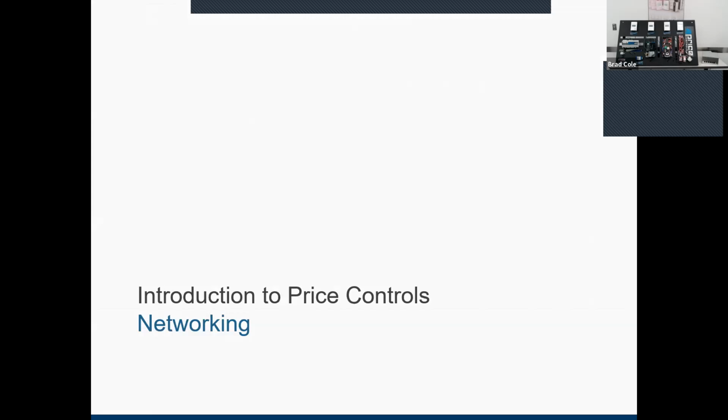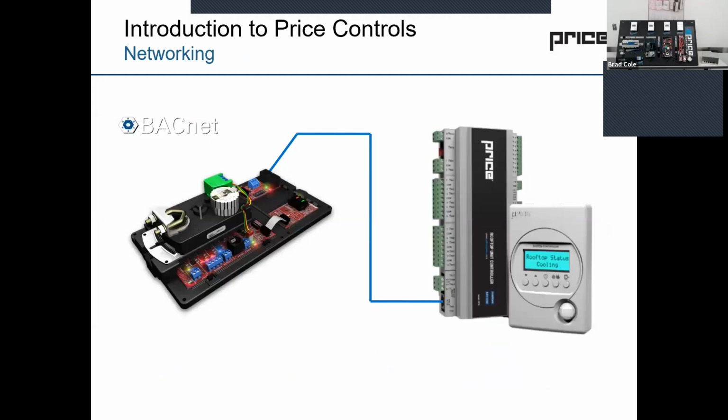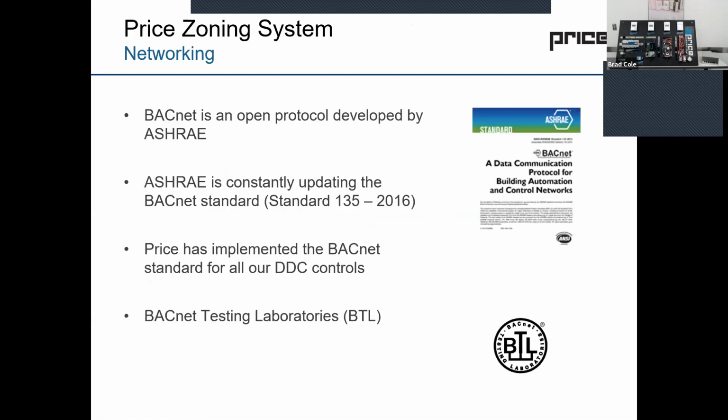Okay, just quickly on networking, just mainly because this is for the contractors. Really what we're going to do here, guys, we're hooking up a network, and I'll show you just quickly on the hands-on behind me in a few minutes. But really what you're doing is you're connecting a network from our main system controller here out to the devices, and we use BACnet. So that's what we use here at Price. The reason we use BACnet is because ASHRAE has a standard on BACnet. So we follow this ASHRAE standard. We're BTL certified, and we follow these standards.